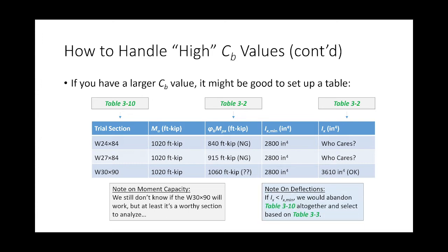Now, I would argue that if you get to this point right here and the moment of inertia still isn't big enough, abandon all this and just find a section based out of table 3.3, okay? Because it's telling you that your shape is not governed by strength, it's governed by deflection, okay? Does that make sense? Okay.